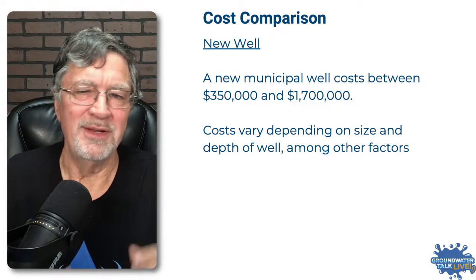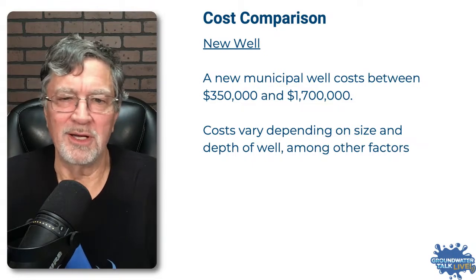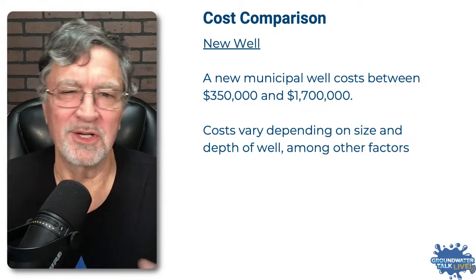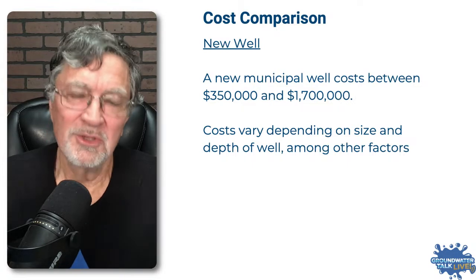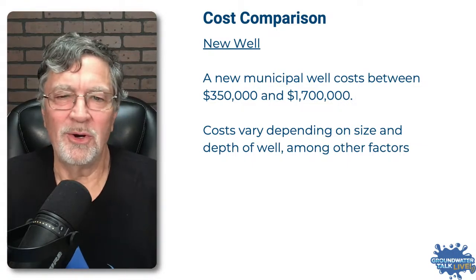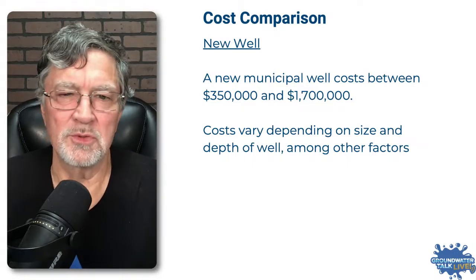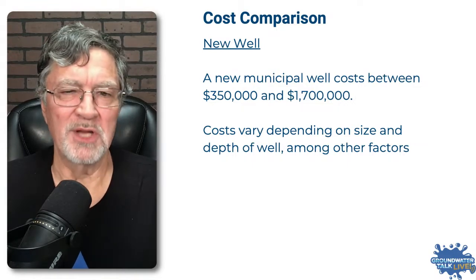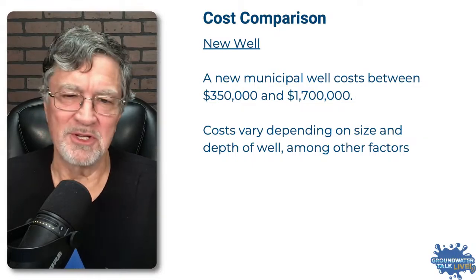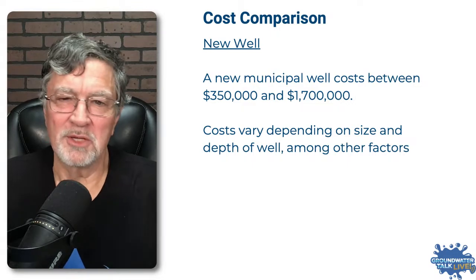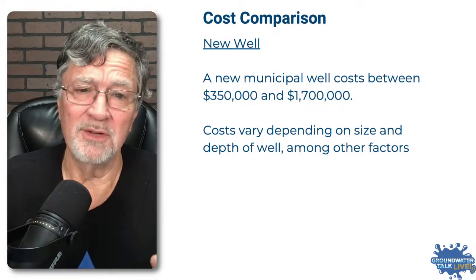It's going to vary based on the depth of the well and the size of the well. Obviously, a 400-foot 8-inch well is going to cost you a whole heck of a lot less than a 16-inch well that goes to 1,000 feet. So clearly a lot of differences. Construction materials, if you're going all stainless steel, then that's going to add to your costs as well. Although I'm generally pretty much a stainless steel guy these days for pretty much everything, because it pays off in the long run. That's a topic for another show. But you can see there's a wide variation there, and on the upper end, it's certainly a significant cost.